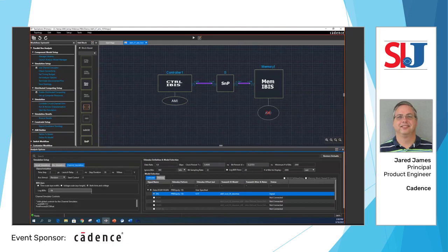And then finally, channel simulation options with step responses for both rising and falling edges. You can change your time step, a delay, or even step duration here. And the bus stimulus can either be random or even.